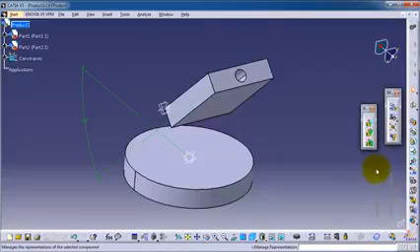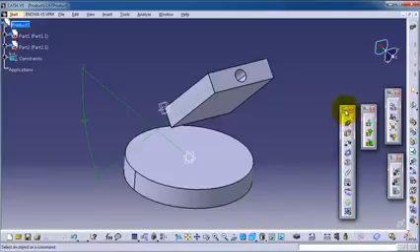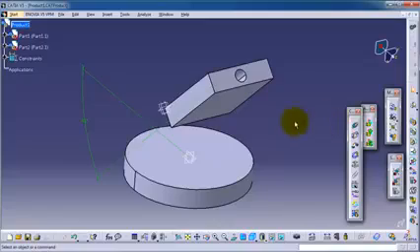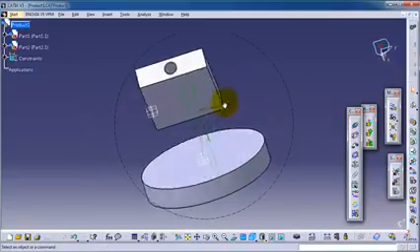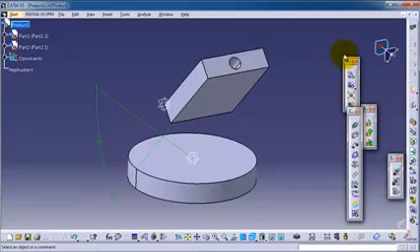You can drag the toolboxes here if you don't see your constraint, and here you see your constraint toolbox, and we already used most of these constraints. Now I am going to show another way to assemble your parts with the manipulation tool found in the move toolbox. So from its name, it's move and gives you the ability to move your parts in different directions.